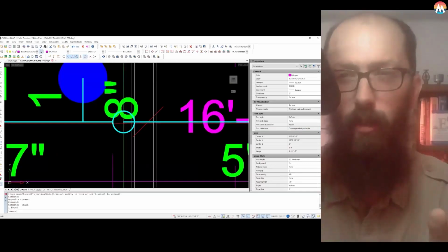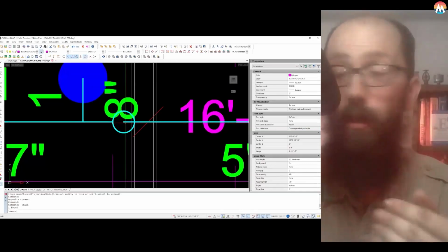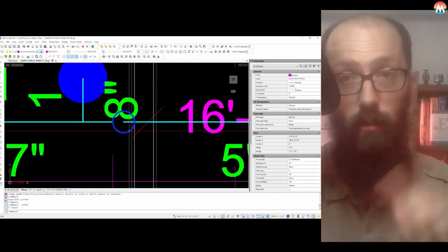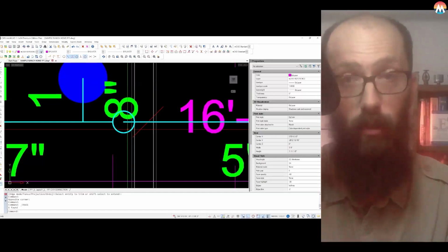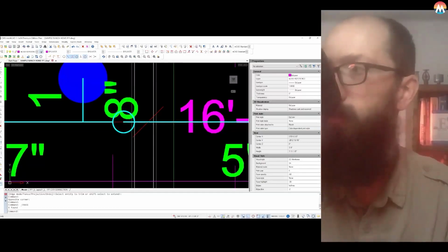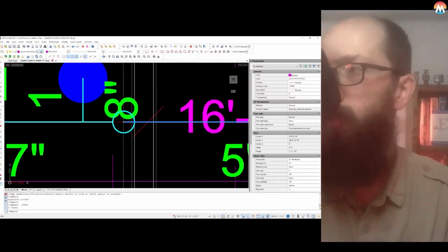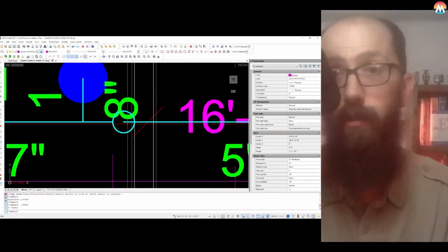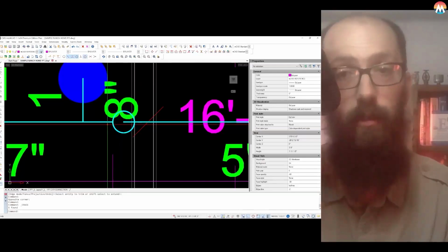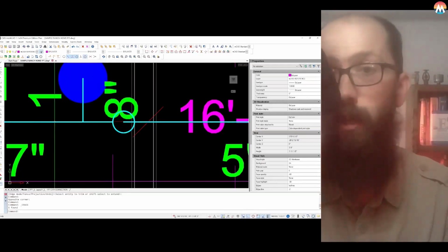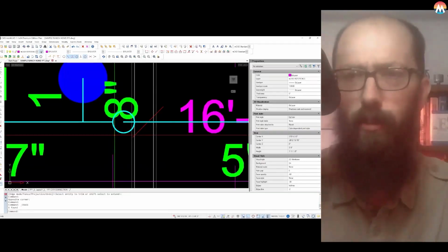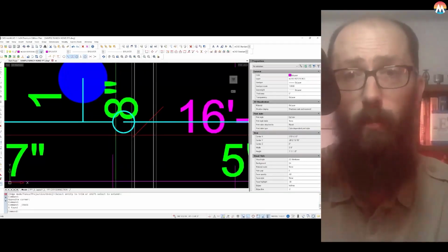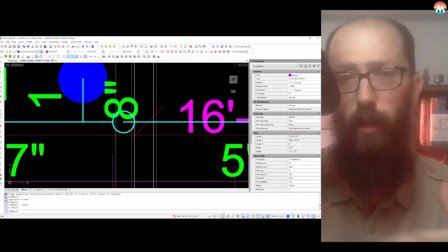You can tell that by the way it's trimmed, because if you were looking down on this in plan view as we are, that's what it would look like, if that makes sense. You would see the top pipe going into a 90, and then the bottom pipe, you wouldn't see the fitting. It would just be coming out of the side of the bottom, right? Out of nowhere, seemingly. So that's what this ideally represents when you're representing vertical pipes.